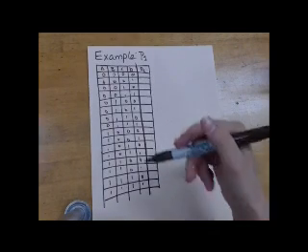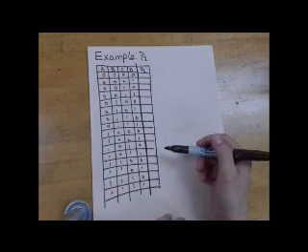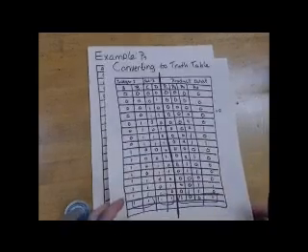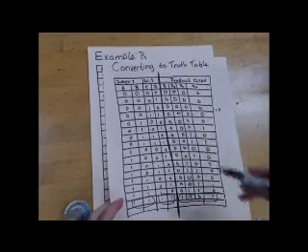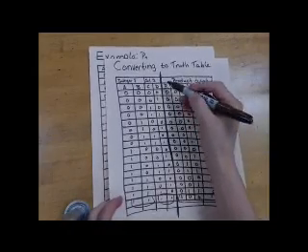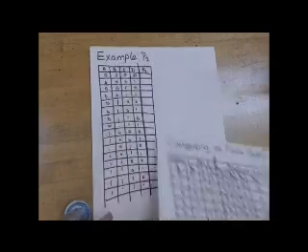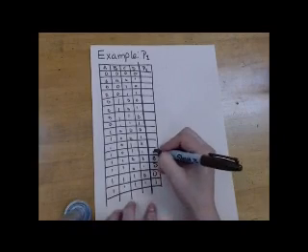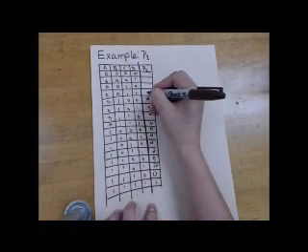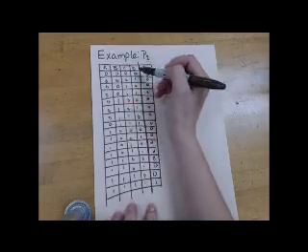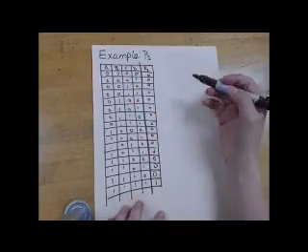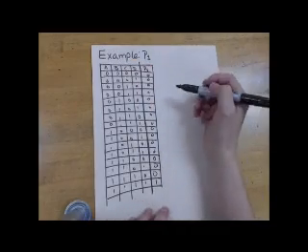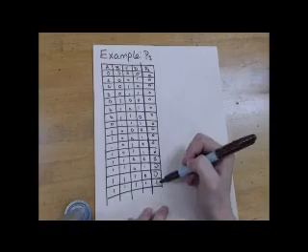So anyways, I just went ahead and filled out the rest of this table. And so what we know for the first input from our gigantic, massive, ugly truth table is that, as we can see here, for P1, all of the values are 0 except when all inputs are 1. So we have a 1 here, but these are all going to be zeros. So now how do we take a truth table such as this ABCD and make it into a logic gate system? So we have 4 inputs and 1 output, and we can see that it's going to be 0 all the time unless all 4 are high.